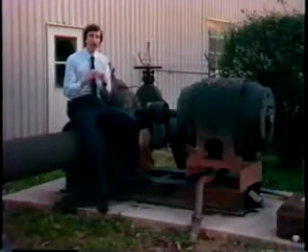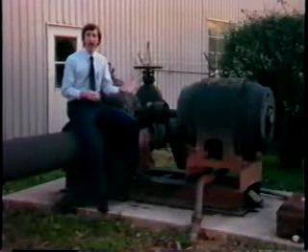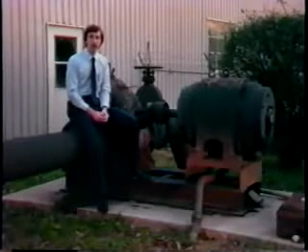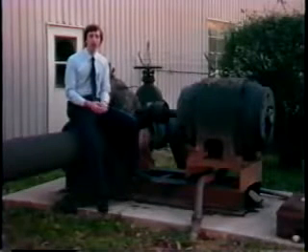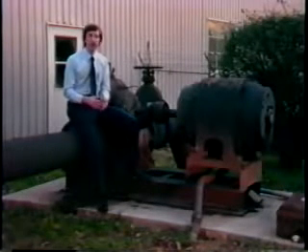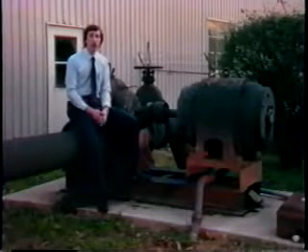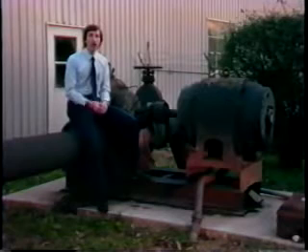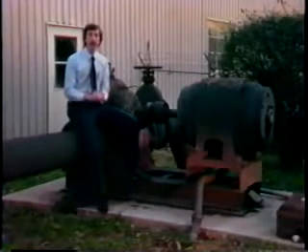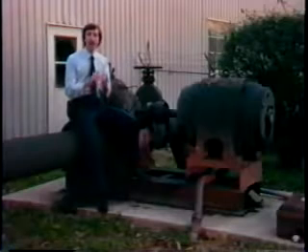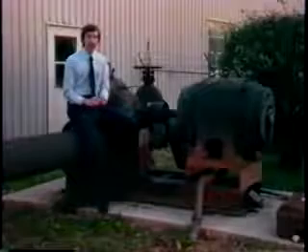So for the best results of the test, corresponding to what would happen during a fire, you want to have as many pumps on as you would during a fire. Now for model calibration, this isn't always necessarily true. You may want to calibrate the model, for example, for the case where all the pumps are off and the system is relying on a tank, as it would during a power outage. So think about what you want the pumps to be doing when you're running the test and have the pumps doing that and find out just what's happening to record it for the results of the test.